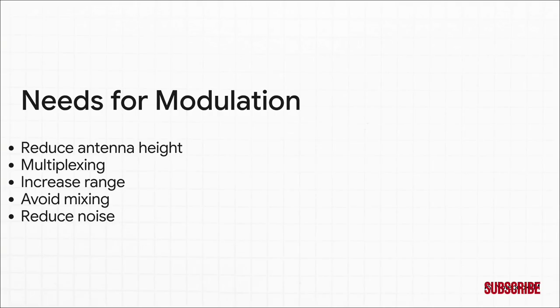This is a heavily tested topic. Why go through all the trouble of modulating? There are 5 core reasons you need to know. Reduction of antenna height, multiplexing, increase in communication range, avoiding mixing of signals, and reduction of noise.